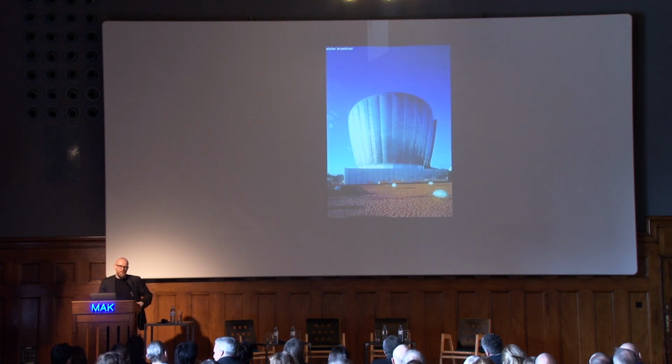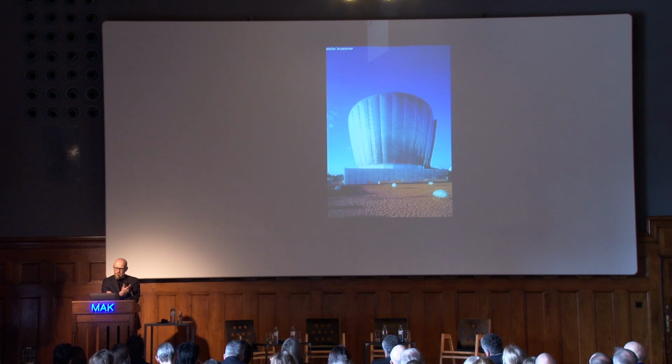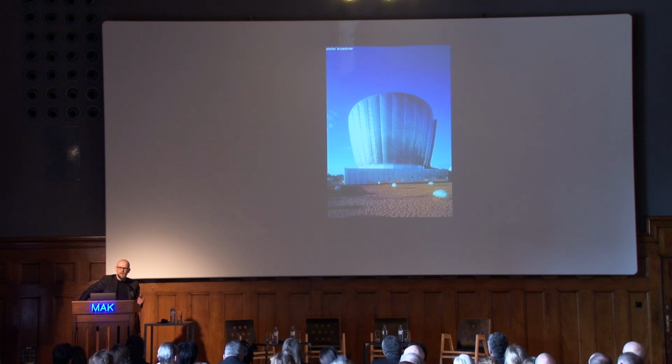We also look at nature and copy things which work well in nature. For example, when we get hot, we perspire, and some animals do too. That means we use water evaporation to cool the building. This was a pavilion built by Dualis System for Expo 2000 in Hanover. They asked us to do a building which basically has no air conditioning system. It was with Atelier Bruckner from Stuttgart. So a building without air conditioning: how do you do it?